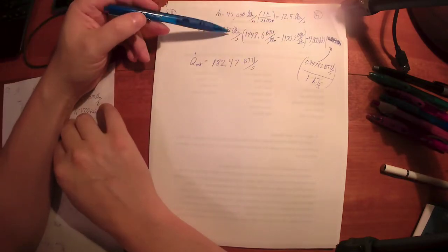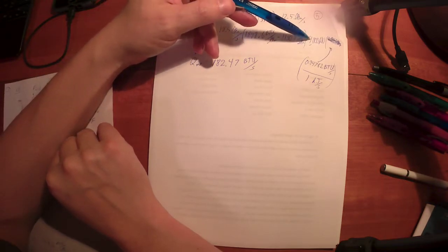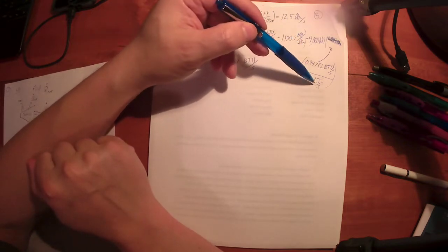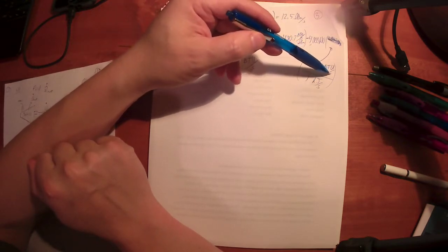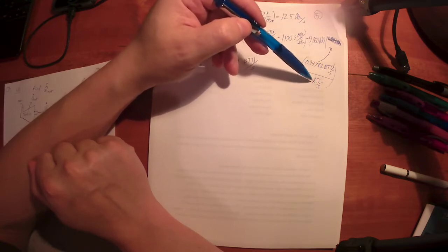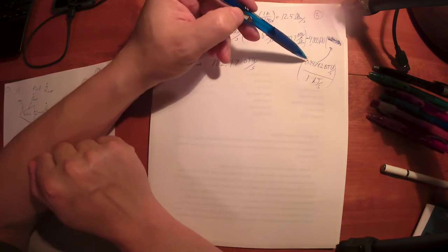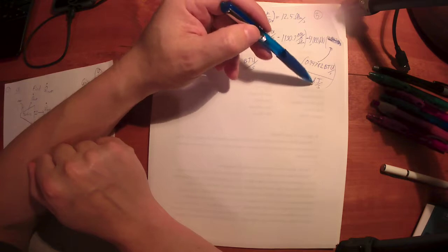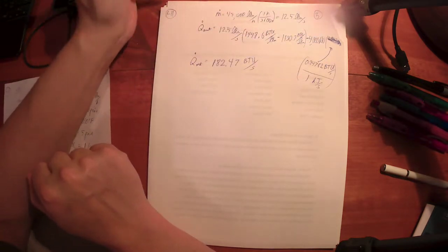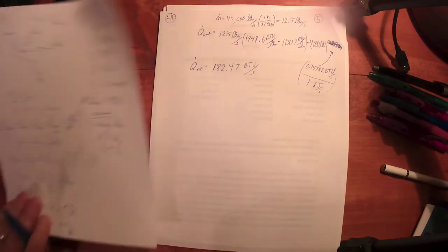Mass flow rate converted to pound mass per second. We found H1 and H2. It's 4 megawatts or 4,000 kilowatts. There's a conversion factor for BTUs to kilojoules. BTUs per second, kilowatt is a kilojoule per second. So for every kilojoule, there's 0.94782 BTUs. So there's going to be the same number of BTUs per second for every kilojoule per second. So that serves as my conversion for BTUs per second to kilowatts. There's some others in there, but that will get you there, right?